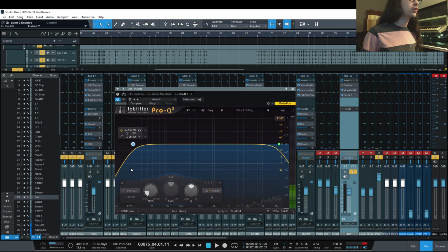So when you block DC and you remove that offset, you no longer can have this super squared off wave, because it's mathematically impossible for something that blocks DC to let something that has DC artifacts in it through.